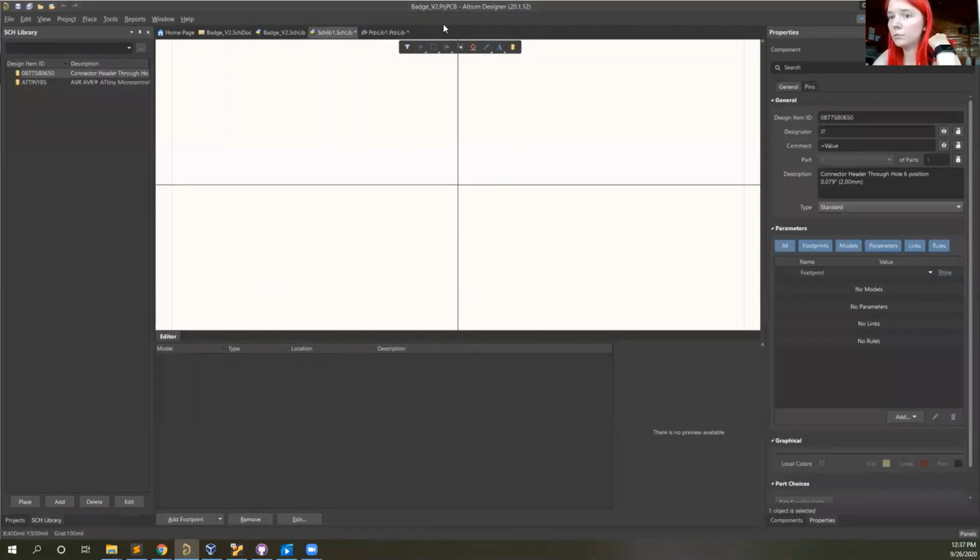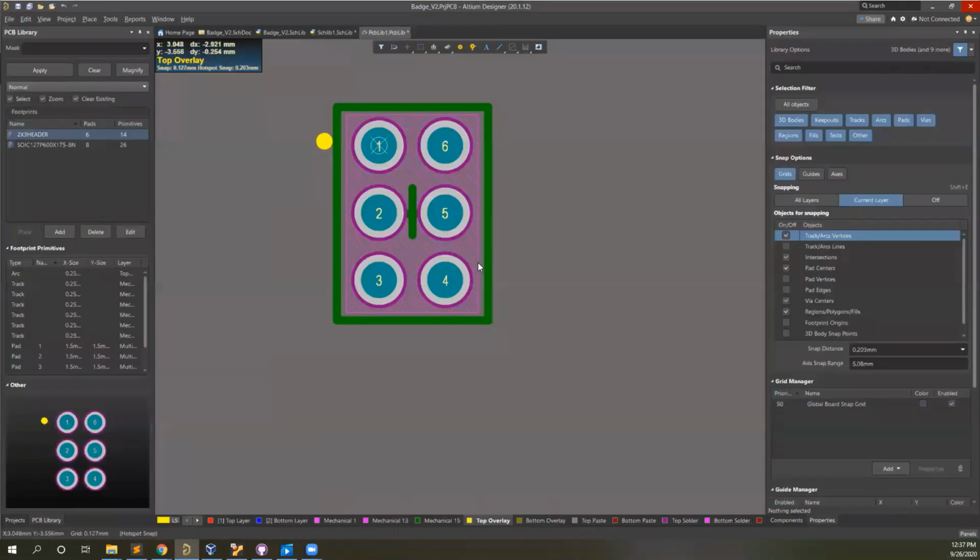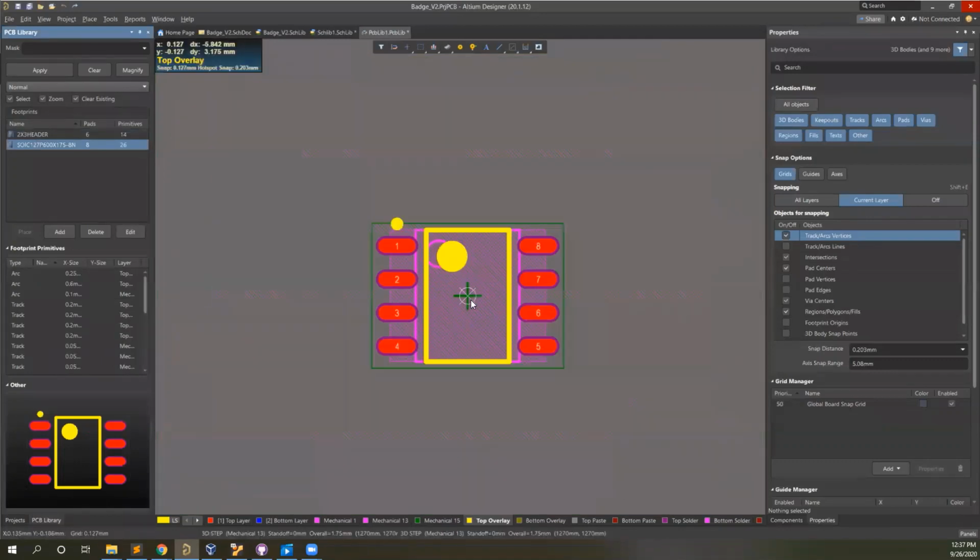So that's that. I'm going to have you guys make the mega part. I'll post more information about that, but essentially I want you guys to do a similar thing that I did with this component. You can either make it by hand or make it with the wizard. I want you to make the AtMega 328P, which I will give you guys a datasheet for and a link to on DigiKey for all that information. And I'll have you submit that to a drive folder just for me to check over it and make sure you're not missing anything important.